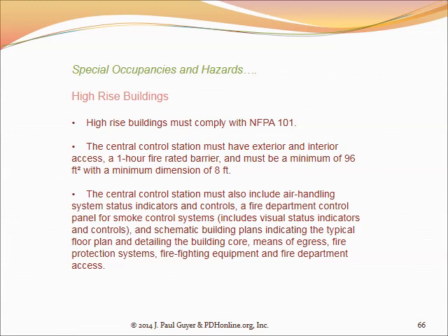And so the concepts have been developed over many years and are well known. And the circulation, the key element there is stairwells. The stairwells are the route that the people in the building take to get out of the building in the event of a fire, and that the firefighters use to get into the building in the event of a fire. And so those stairwells need to be constructed of highly fire-resistant materials like concrete, CMU block, poured-in-place concrete.